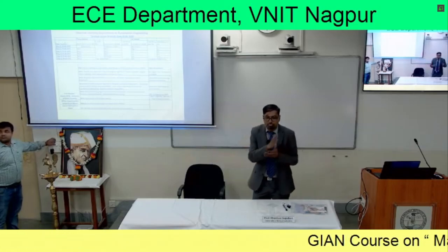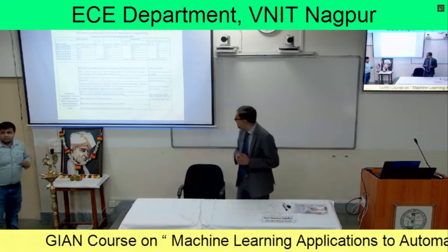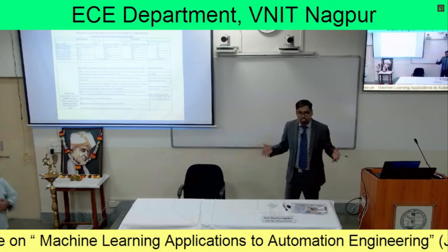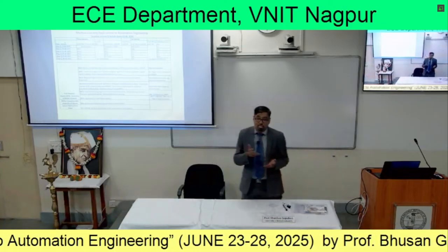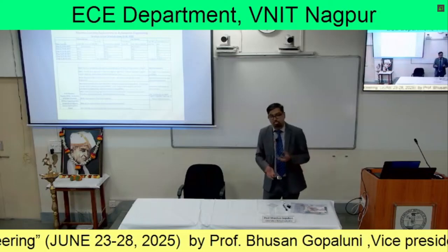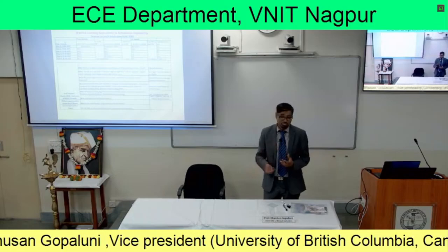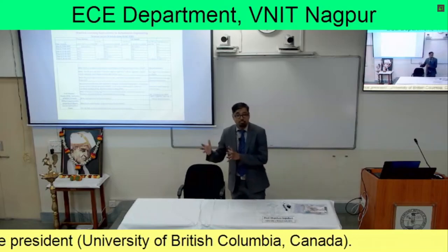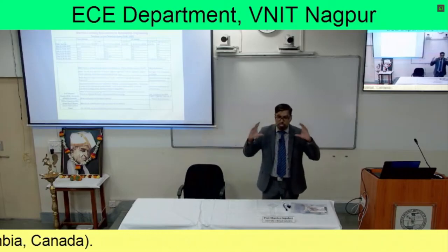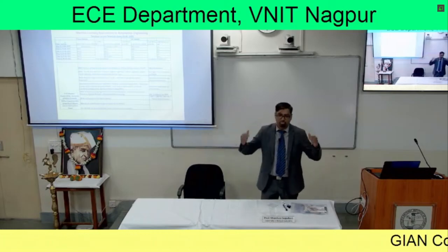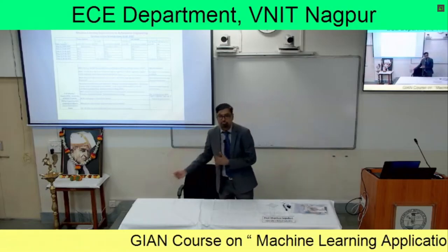So what it means is if your inputs and outputs are, let's say, as an extreme case, constant, not changing at all, then you will not be able to invert that matrix, and therefore, you will not get a reliable model, right? Then how do we get a reliable model? We have to make sure that the inputs are changing. They are perhaps random, right? And then you will be able to have a good condition number for that matrix that you have to invert. When that happens, then you'll get a really good, reliable model.